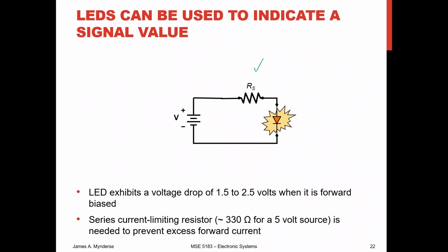We are going to need to specify that current limiting resistor. And so how bright do you want it? We'll choose your resistance value appropriately, but you definitely want to have something in there so that you do have some control over the current going through it, because again, we don't want to exceed the power dissipation of our LED, or we could damage the LED.